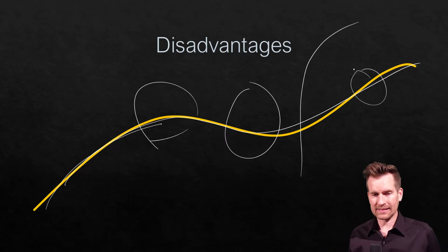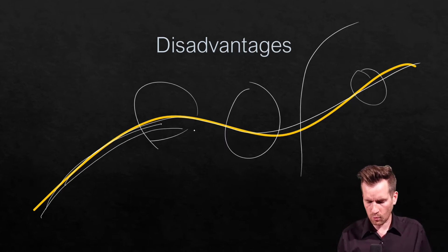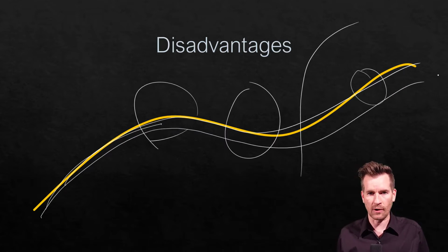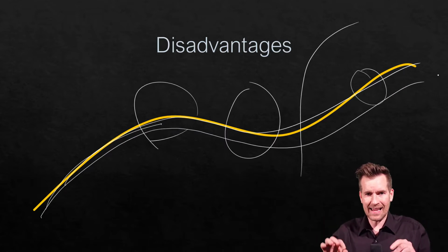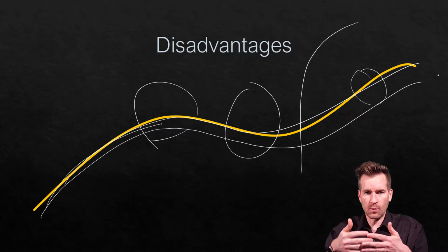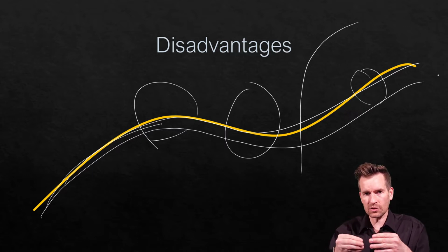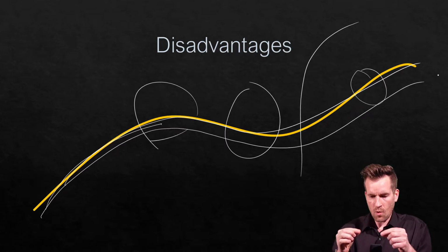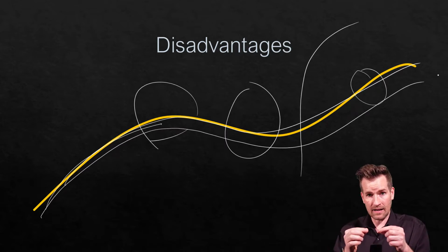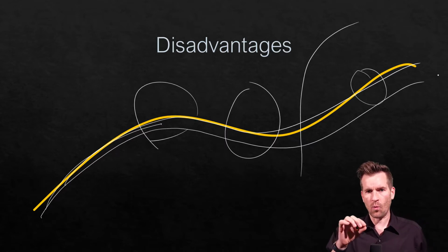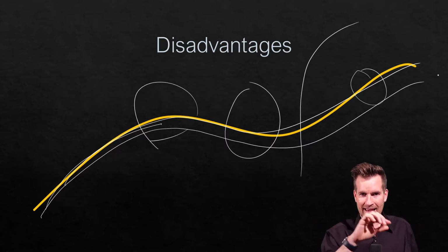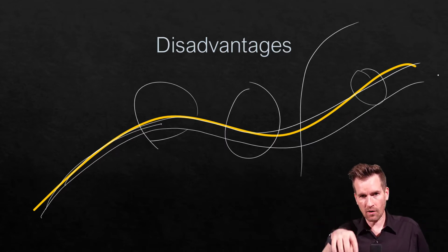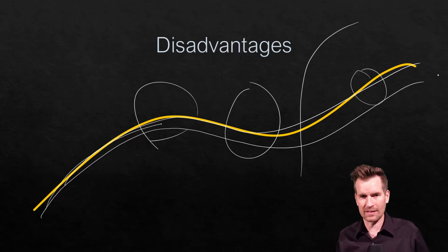Another example is that a lot of times we'll run cables next to each other, or even within the cable, there are multiple pairs running next to each other. And so those lines will interfere with each other with this electromagnetic interference. We call that crosstalk. When you get bleed over into the next line, that's what we call crosstalk. So that is also a disadvantage of copper lines.